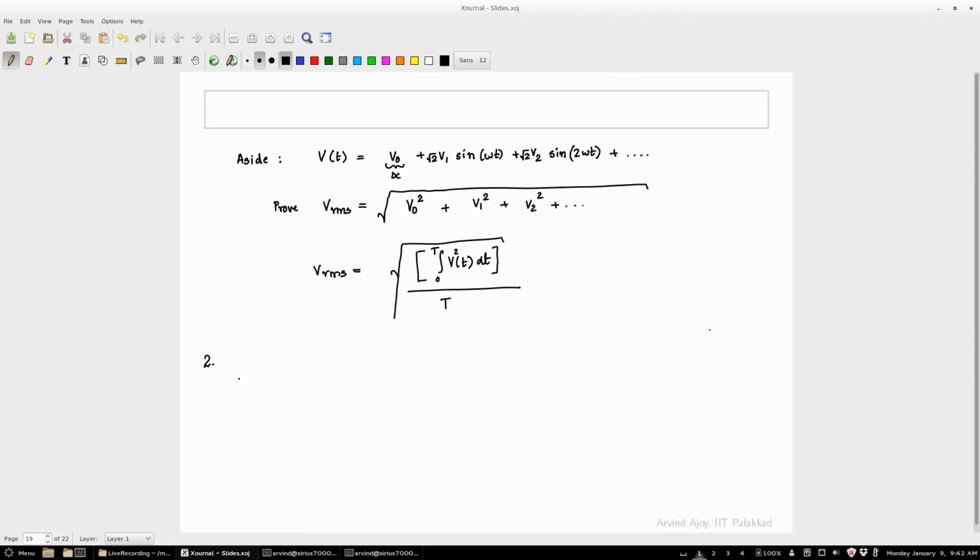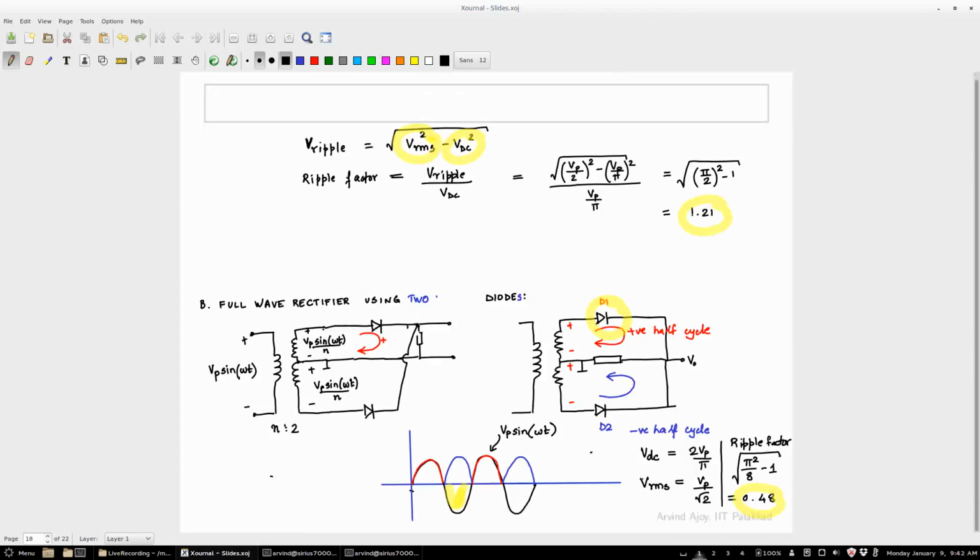you're making a power supply, your power supply will be rated for some value of current. You cannot draw more than that amount of current from the device. So that will put a restriction on what diode you actually choose; it should be able to sustain that value of current. You get some diodes which will sustain, say, 10 milliamps. Usually power diodes sustain amps. However, your small diodes will sustain only 10 milliamps, 100 milliamps. So take a 100 milliamp diode and put it in a place where you may be drawing 1 amp. What will happen? It will burn off. So that's an important specification.